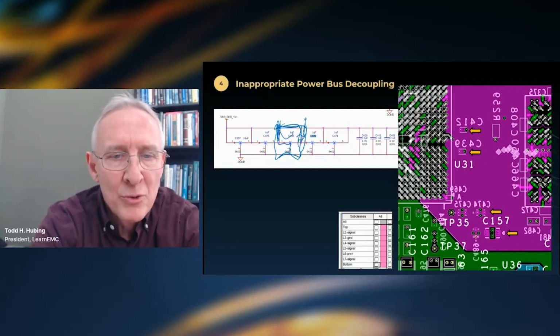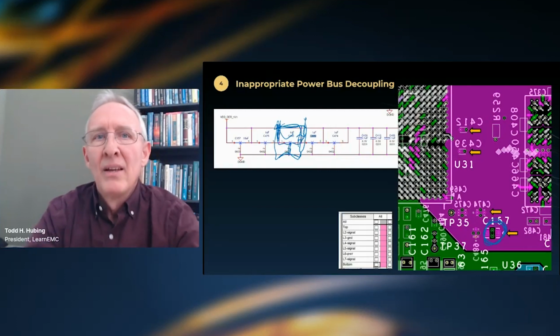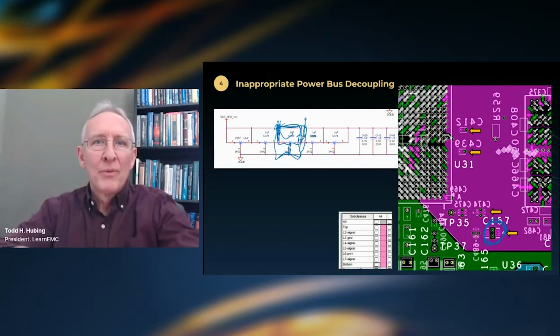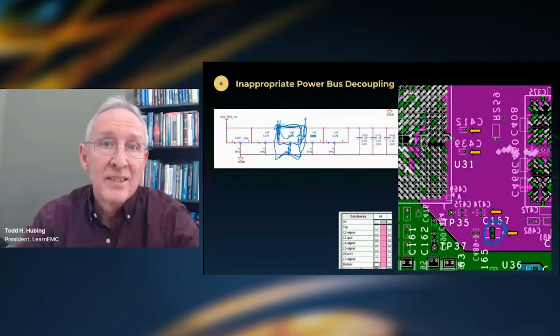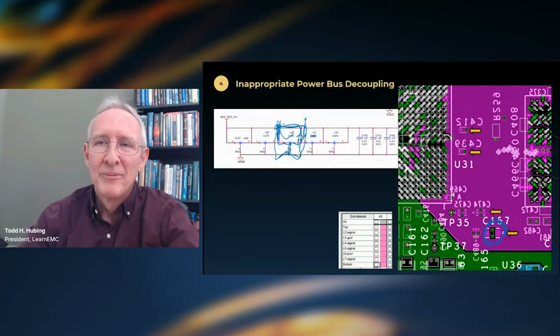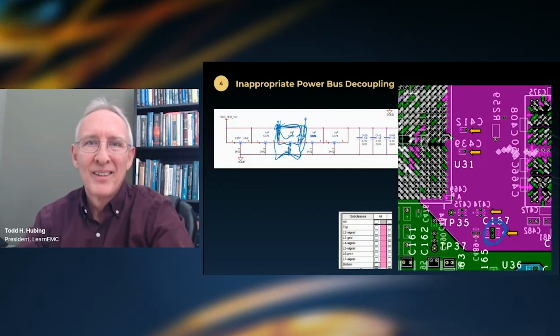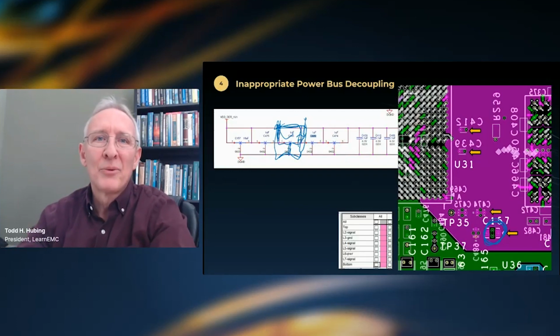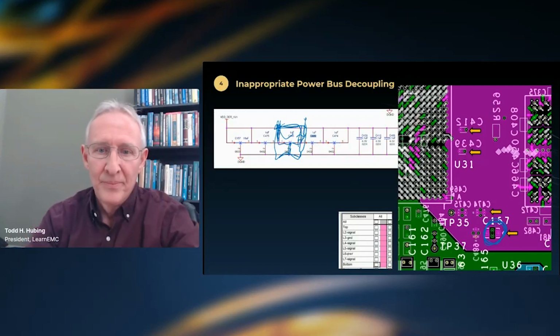my voltages come down to one single pair of vias in the center. Here we're showing it in the layout right there. There's one of them. But we don't want our grounds to come together before they connect to the ground plane of the board. We'd be better off with 2 capacitors with separate grounds, particularly if we go any distance. I'm not saying these capacitors are terrible, but they are not providing an advantage that's equivalent to their cost add. They're really inappropriate. It's the wrong design for power bus decoupling. It's exactly the right design for filtering differential signal lines.